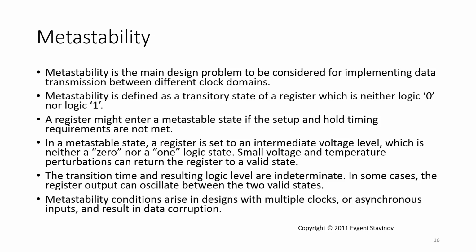But we know for any response to happen, the data should be available, the 1 should be there before the rising edge by what's called setup time. Not only that, the data should remain 1 even after I reach the rising edge of my clock, by a hold time.